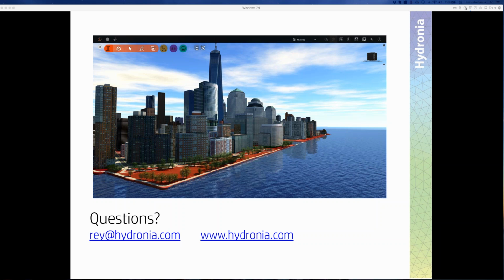What happens to your coastal flooding simulation when your base model does not include the entire bay, channels, rivers, or other coastal water area? Will the RiverFlow 2D simulation be accurate if your model does not include the entire boundary of where water might spread? Well, it depends. It can be or it cannot be. It depends how important that water body is or how much it influences your area of interest.